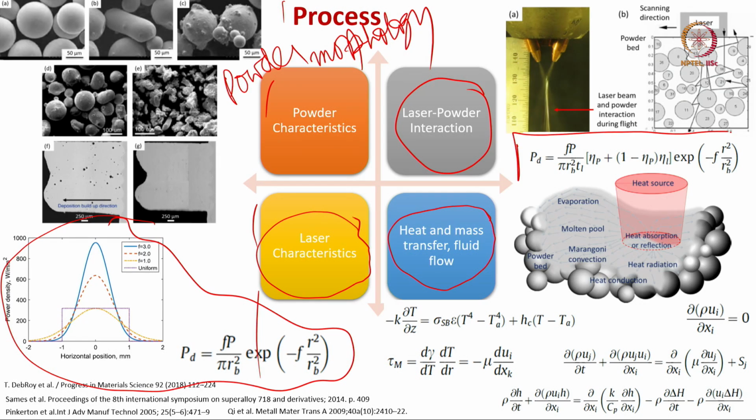In the right part also, this particular equation I have described to you in the last slide, that is how the laser power distribution function is changed in the presence of powders, and what you can see is that these particular parameters are actually present, which are not there in the case of the laser power distribution without powders.